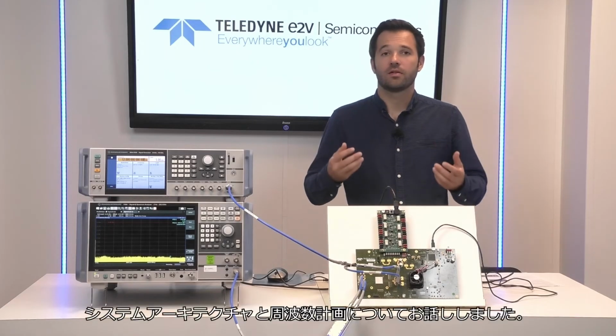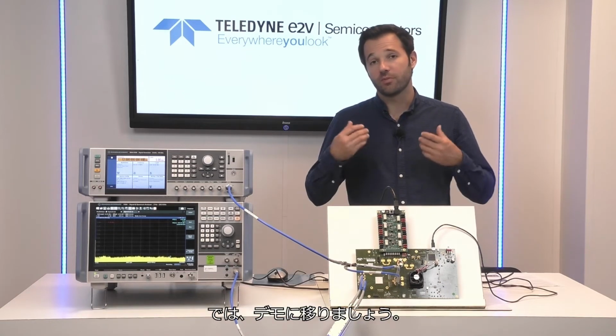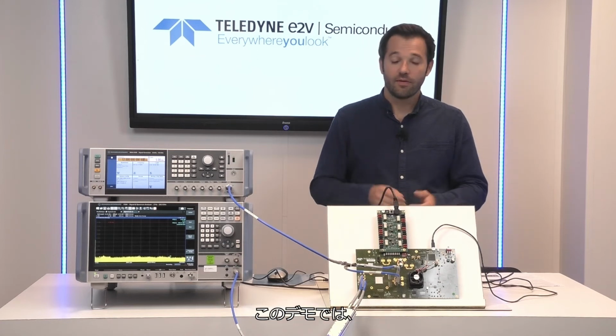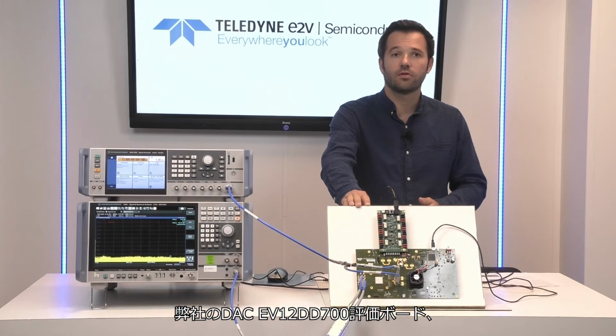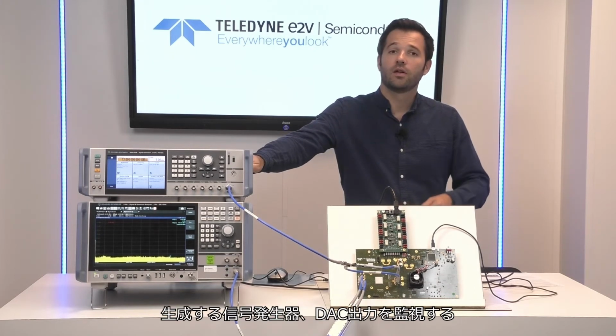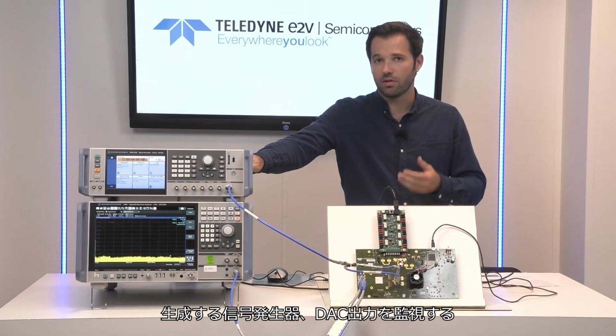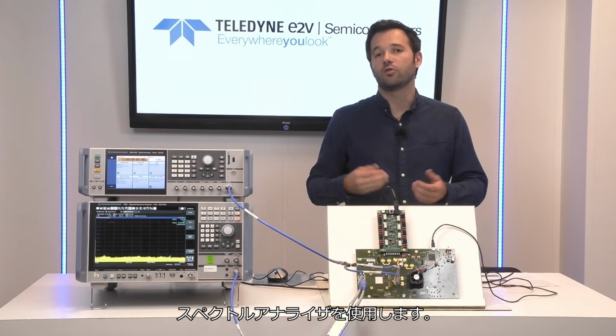We have seen system architecture and frequency plan. Let's get to the demonstration. For this demo, we use one of our DAC EV12DD700 evaluation board, a signal generator to generate the 12 GHz DAC input clock, and a spectrum analyzer to monitor DAC output.